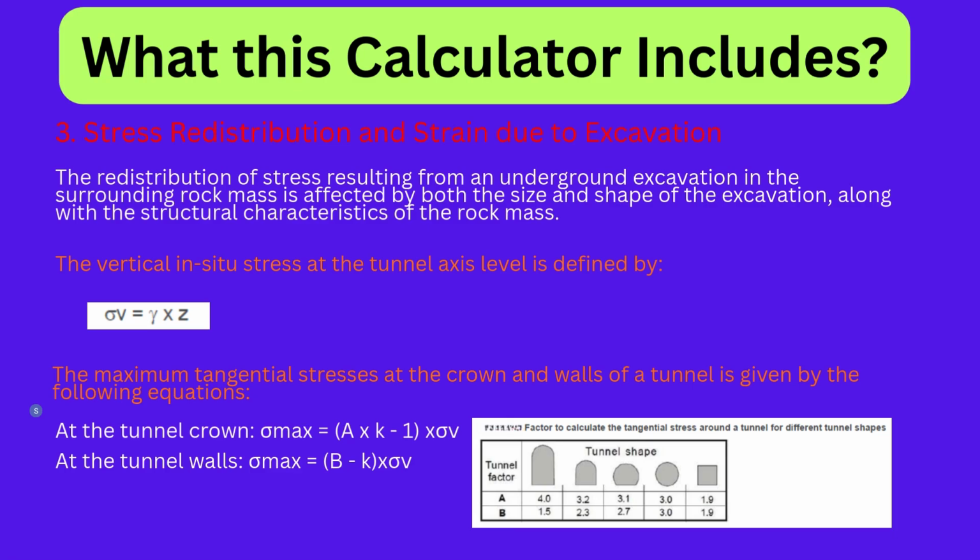In the calculator, you will also calculate strains around the tunnel, which will be used to determine squeezing conditions in the tunnels. In the next slide, we will see how the parameters from the Hoek and Brown failure criteria are used to determine squeezing condition in excavated tunnels.